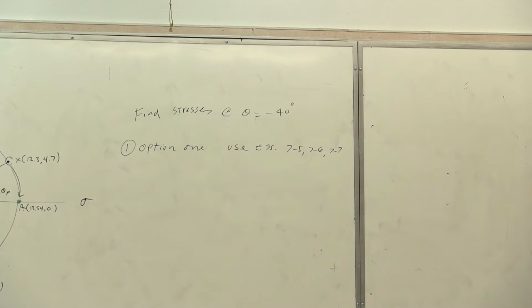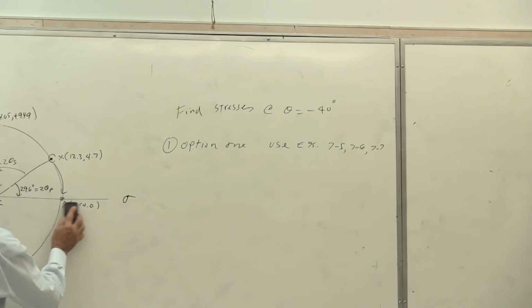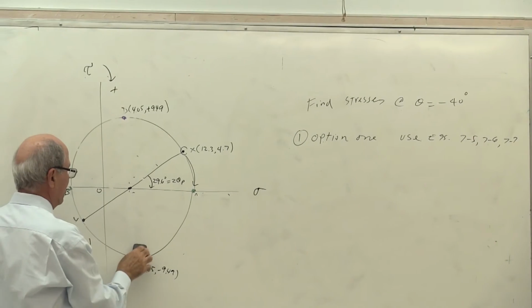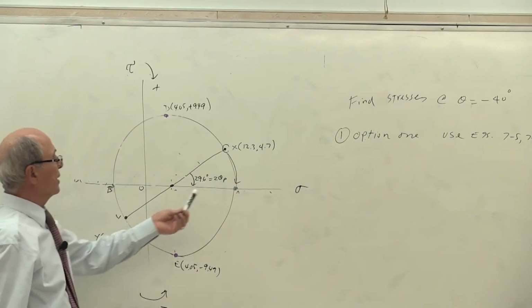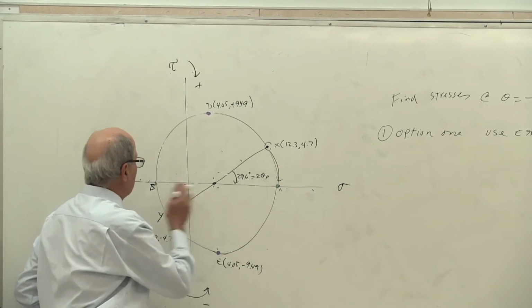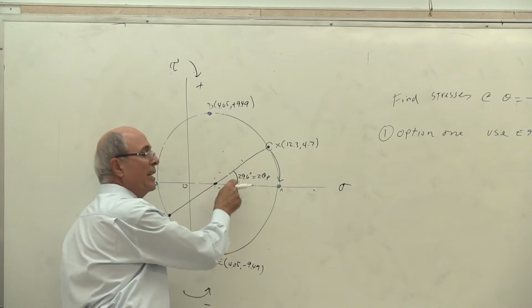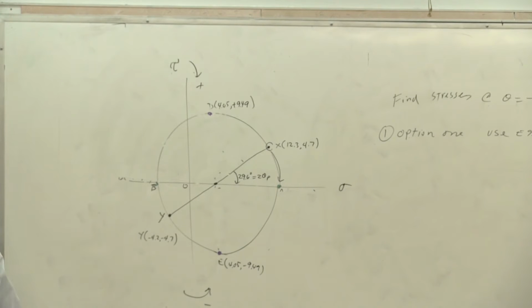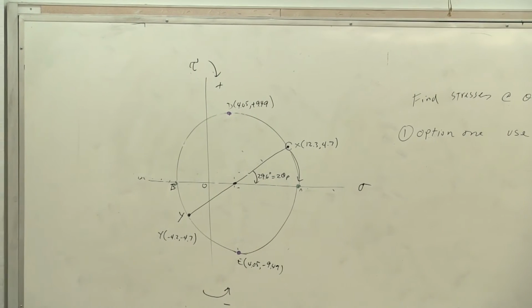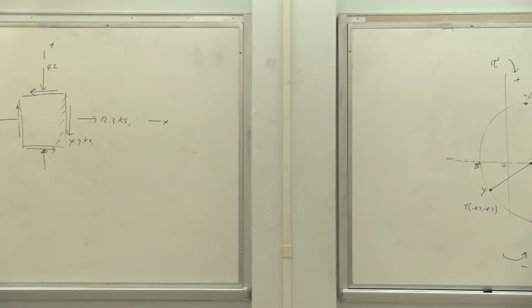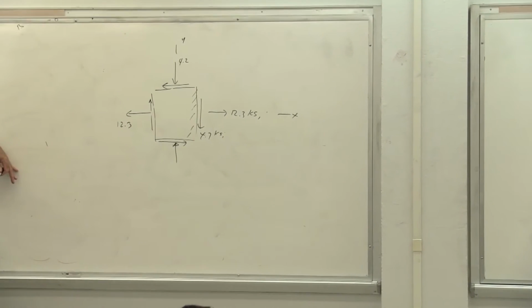That's something some of you have already done or not. But to do that, you don't need all of this information. None of this is required. However, drawing the Mohr circle is essential. Is that correct or not? At least to this point. You need to calculate, put the x and y there, which we did. Correct or not? Yes? You don't need to calculate A and B. That's not necessary. But you need this angle. That angle is 29.6 degrees. Now, what's the object of our exercise here? It is this, guys. We don't want to go to the principal stresses. We don't want to go to the maximum shear. We want to find the stresses at minus 40 degrees.